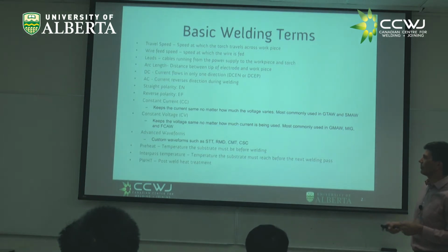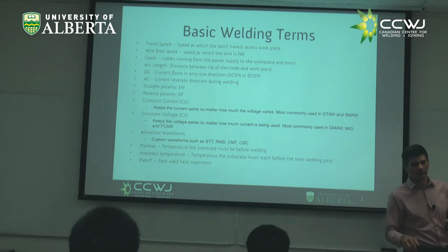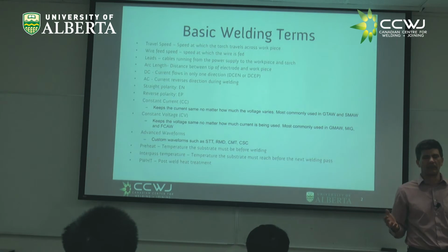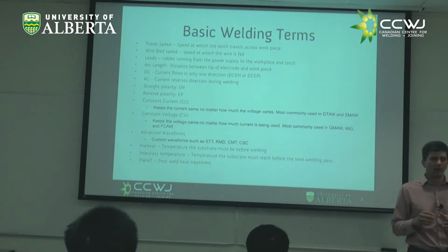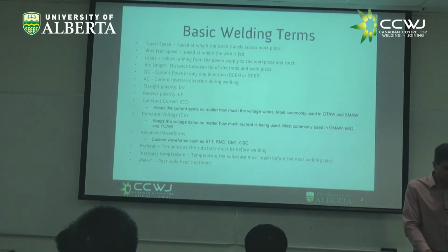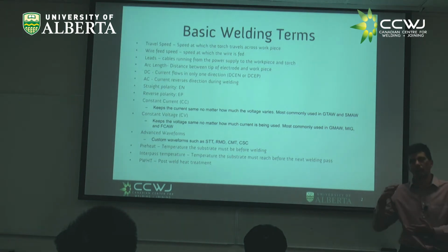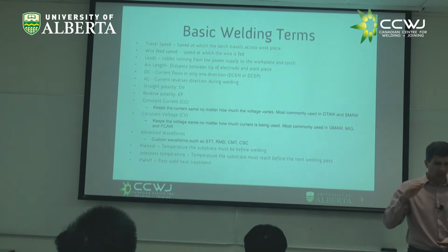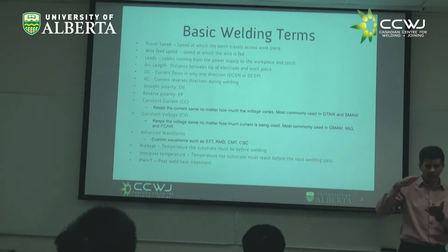This is quite common. Three more common words. Preheat. So let's imagine we melt steel. We're welding steel. Steel will always melt at the same temperature. Now, if the steel is at room temperature, the jump to melting is a given jump, and the heat transfer associated with that delta temperature is whatever. But if you're welding at -40, the jump is even bigger. If you're welding at 200 degrees C, the jump is smaller.